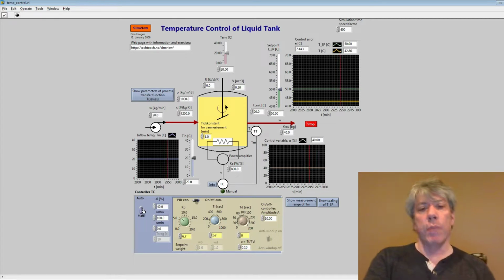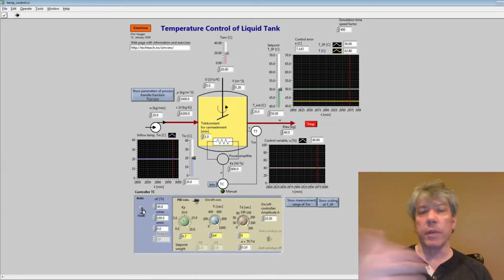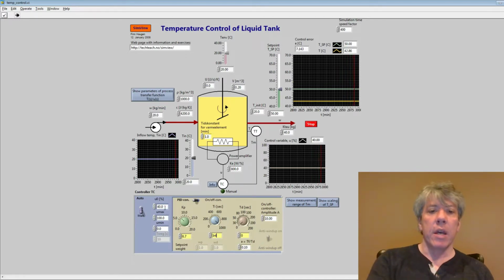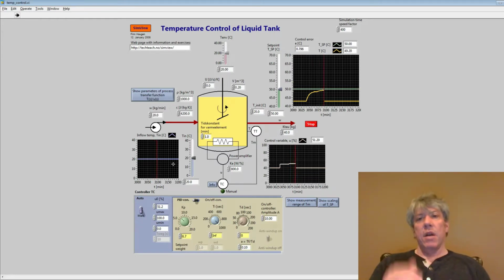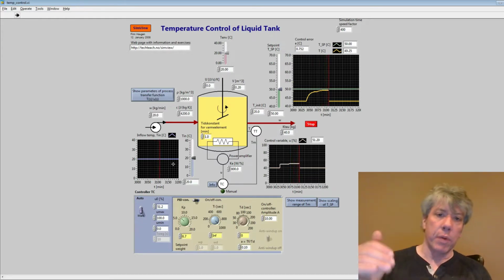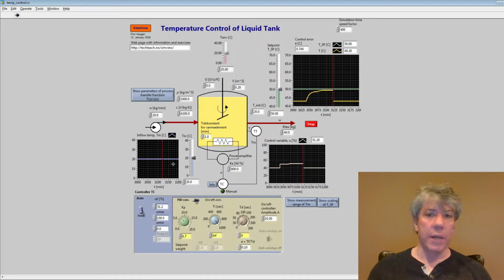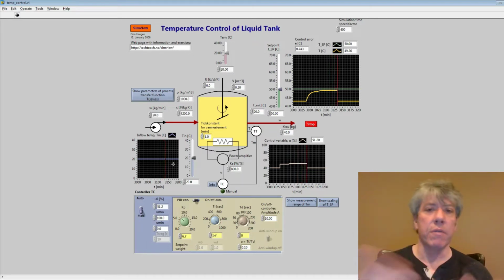Now at this point, most students will go into automatic mode and try to measure the system's ultimate gain and period, but that's a mistake. One of the things that students often forget is you've got to drive the set point to the process variable. And you might say, well, if I can do that manually, I mean, after all, 50% is getting me pretty close. Probably, what is it, 51.2%, I think, something like that. If I can drive the process variable to the set point by myself, why do I need a controller?